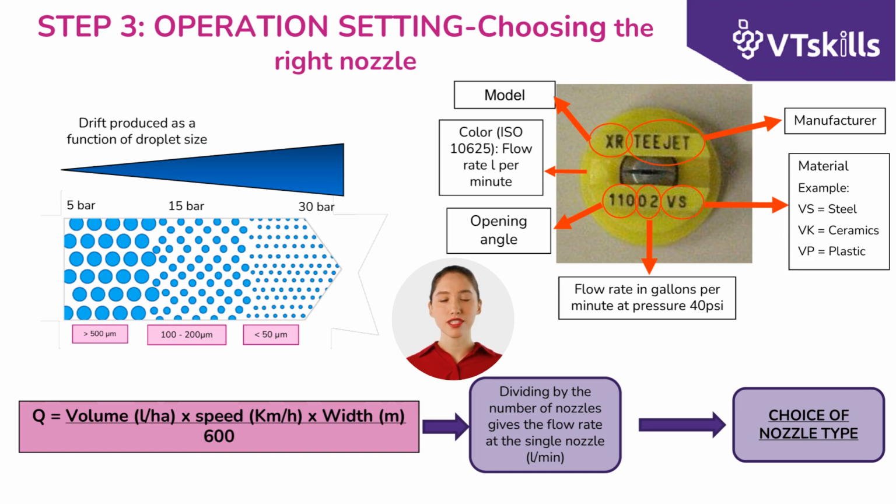The next step is the choice of spraying criteria for the machinery. Sprayers can be divided into low-volume machines, that is, less than 350 liters per hectare, and medium-high volume, up to 500 liters per hectare. Low-volume machines, better known as pneumatic, use the Venturi principle to atomize the mixture. The result is very homogeneous droplets, with a fine diameter of 100 micrometers.